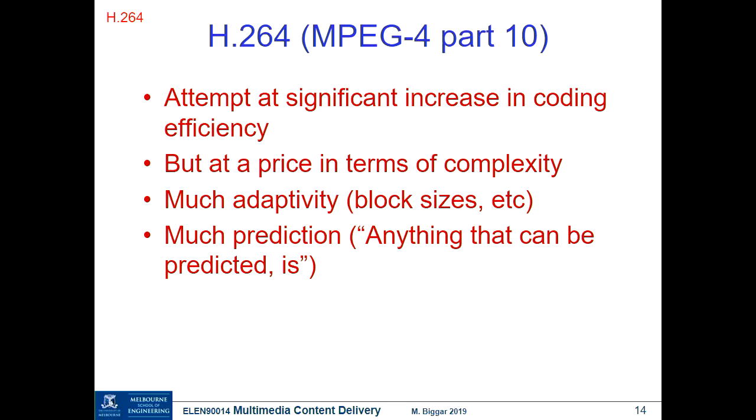What about the motion vector? Does it include when we send it to the decoder? So the motion vector, as you said, is side information. Does it tell the decoder where to search for the match? Normally we send the motion vector. The encoder sends the motion vector to the decoder. Is it to tell the decoder where to search for this block of pixels?